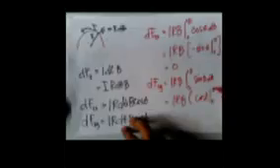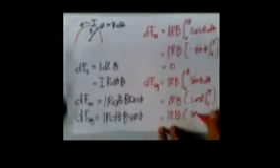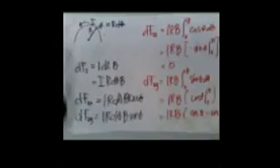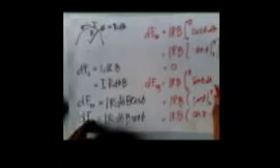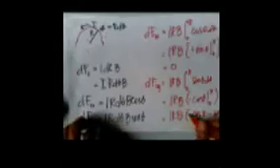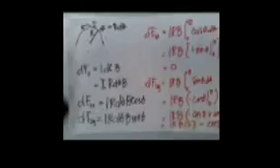The integral of sine theta d theta is negative cosine theta. So IRB times negative cosine theta from 0 to pi. We have cosine 0 minus cosine pi, which gives IRB times 2. Therefore 2IRB. So this is the dF2y.